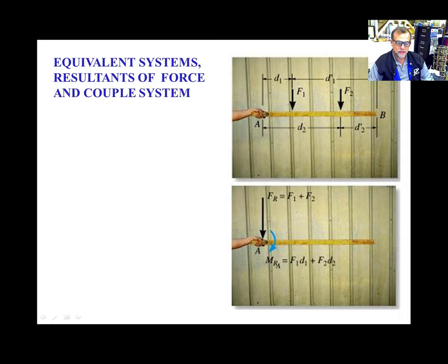And this is for the system externally, not internally, because internally it is different. Internally, if you have the force applied there, there are going to be stress concentrations at that point, and it's going to suffer different things. But externally, in the hand, it is equivalent to having these two forces applied here as a resultant force there, plus a moment.